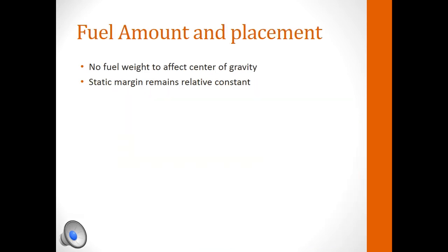Since our aircraft is all electric, we do not need to worry about the fuel amount or placement. However, the placement of the battery is still of importance to our design. Our group decided to put the battery near the center of gravity of the aircraft so that the battery does not affect the moment about the longitudinal or lateral axis.